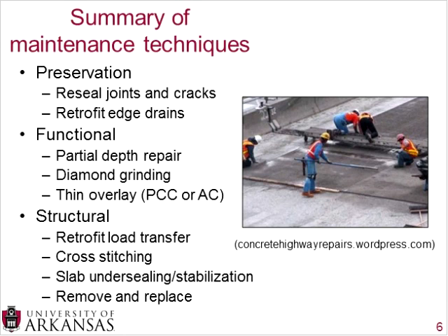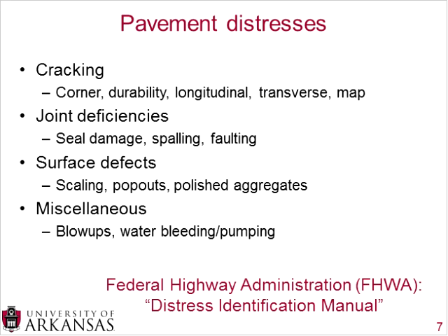And then finally, a very common structural technique is remove and replace. And if you're driving down an interstate, a Portland cement concrete interstate, sometimes you can see new small slabs that are between old slabs. And this often happens because deterioration often occurs around the joints of the Portland cement concrete pavement, and they simply remove and replace about 1 to 2 feet on each side of that old joint and put a new slab of concrete in there. And that's an example of removing and replacing.